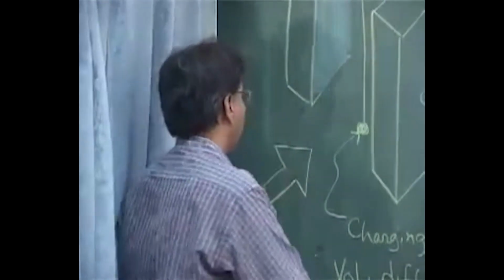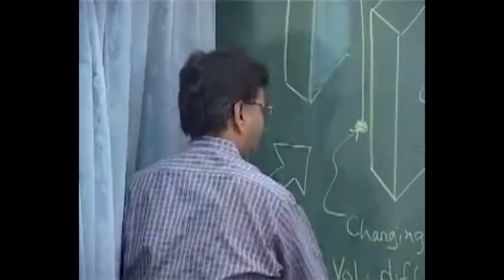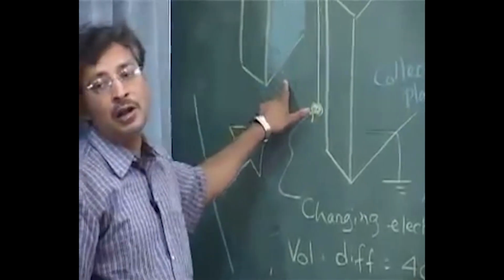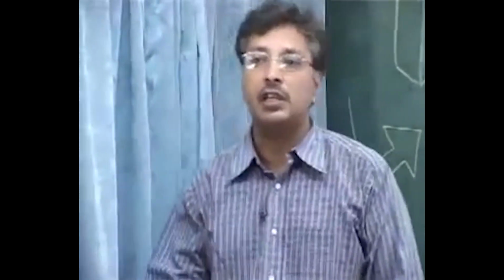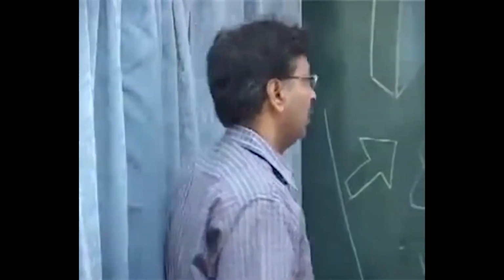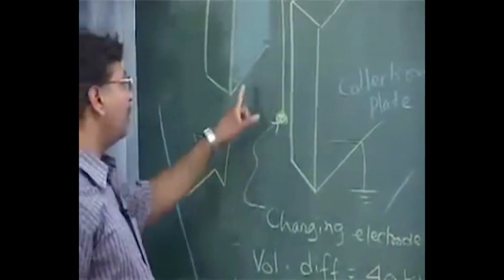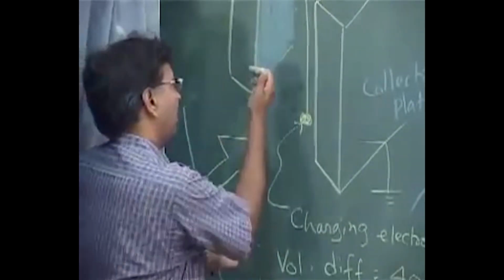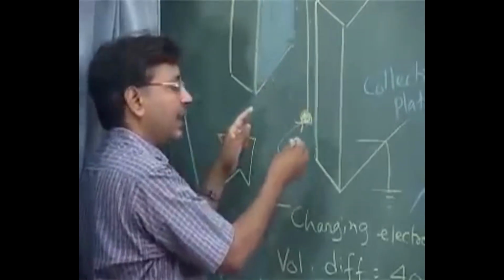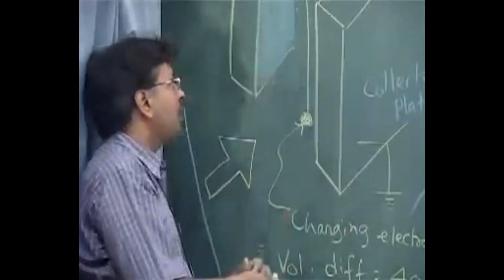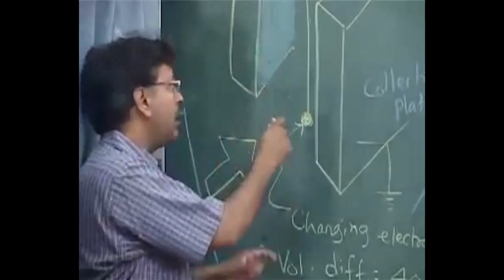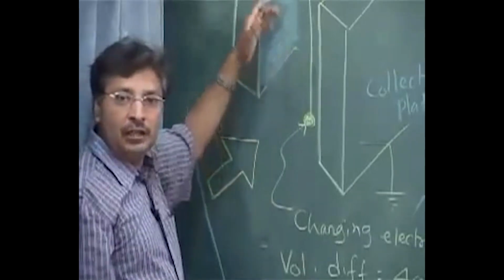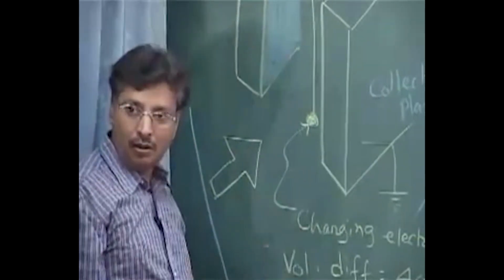And once these are there, underneath this one there will be a hopper, okay, and then there is some operation called rapping operation, R-A-P-P-I-N-G. What we do in the rapping operation is, there are some kind of hammers, with some mechanical movement, they can come and hit the plate very hard, then again they can come around and hit the plate, and once they hit the plate, the dust will fall in the hopper, okay.